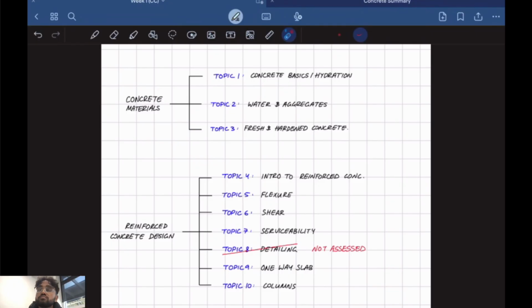I'm not sure what's in that either, I'll be honest. But they do talk about mineral admixtures, curing concrete, all that kind of stuff. It also touches on some of the properties of hardened concrete, like compressive strength, which is the most important one. So characteristic compressive strength after 28 days. That's what we use in the industry to determine the compressive strength that we need to use.